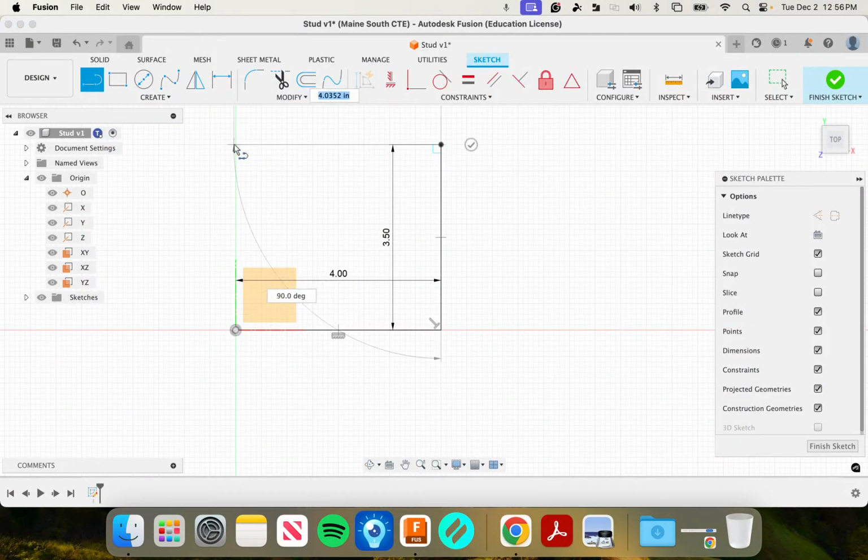Left click there. Now, as I'm drawing with individual lines, one of the things Fusion will do is if I go down to a known corner or point, and I hover there and I bring things back, it will kind of go, hey, were you down there for a reason? Did you want that line there to be parallel and potentially aligned with that point down below? And in this case, I do, so I'm going to go ahead and use that and left click.